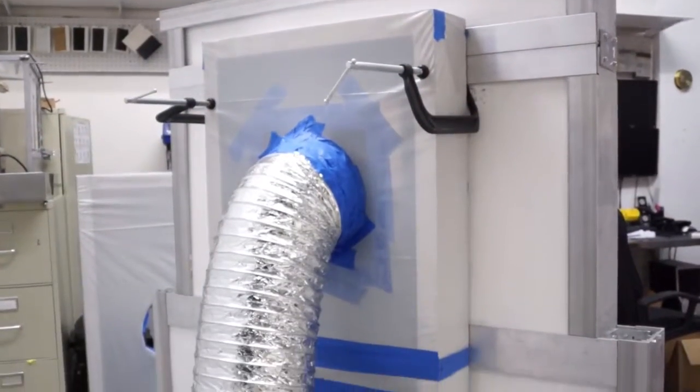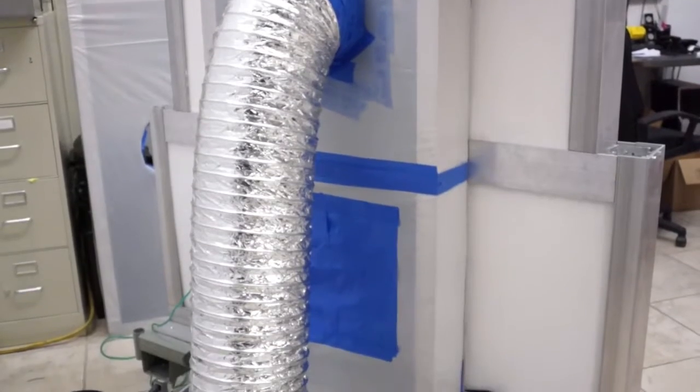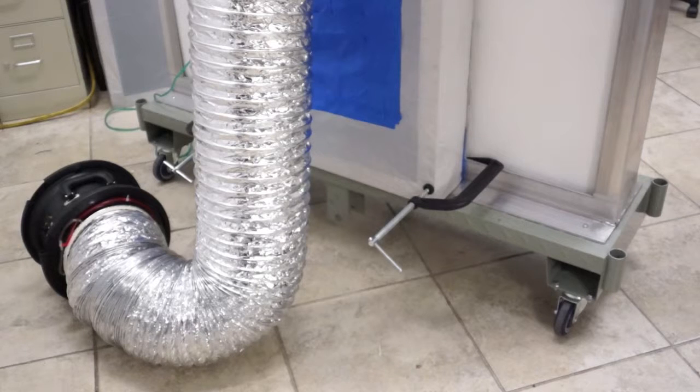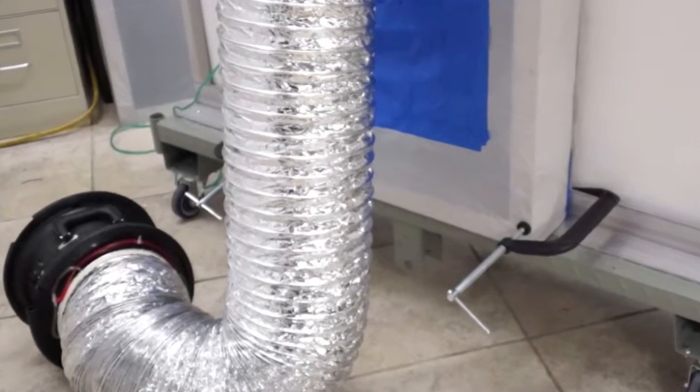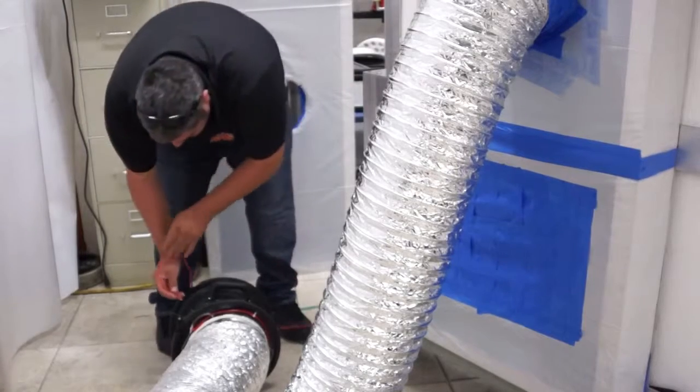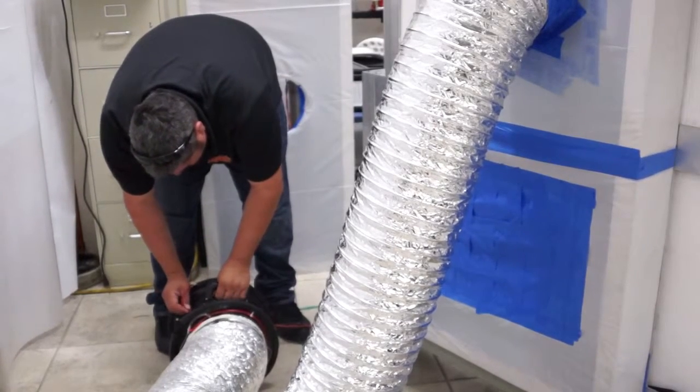Today we are running an air infiltration test, measuring and comparing air leaks in both a standard window and a backup window. We will then calculate the energy savings based on the difference of air convection and wasted cooling air. Here we have the testing equipment set up on the windows. The blower is connected to the air chamber by flexible ductwork. The chamber is attached to the wall using the clamps for a tight seal. The green tube is a sensor that measures the differential pressure between the environment and the interior air in the chamber. We will be using a blower to pressurize both windows one at a time.